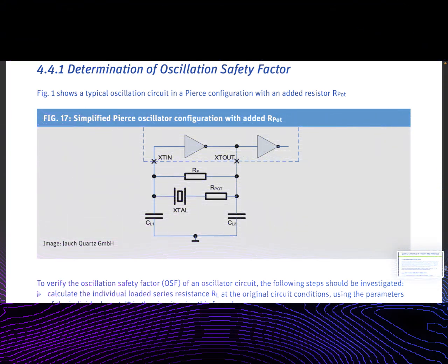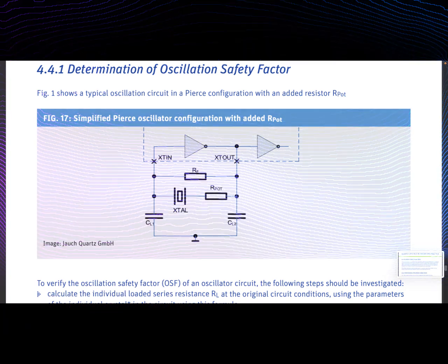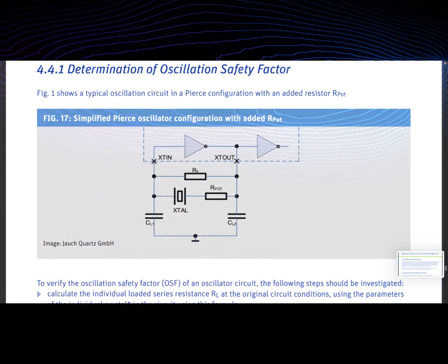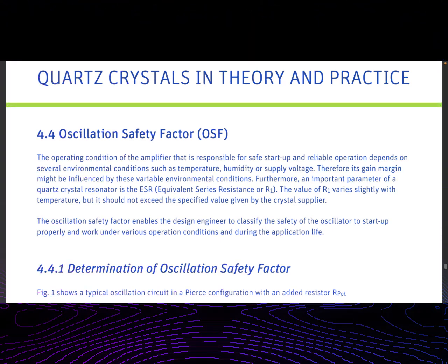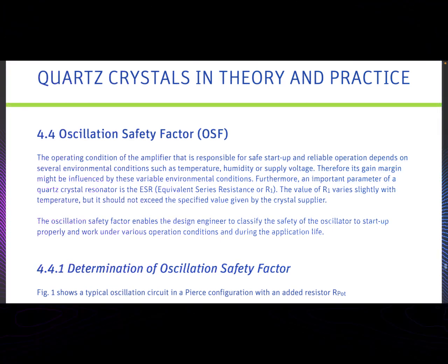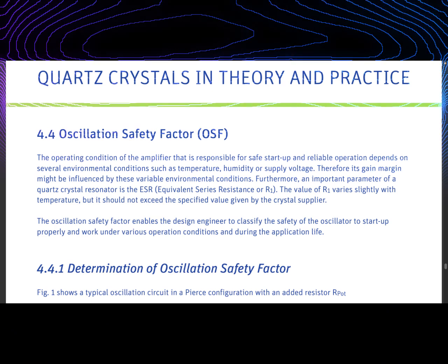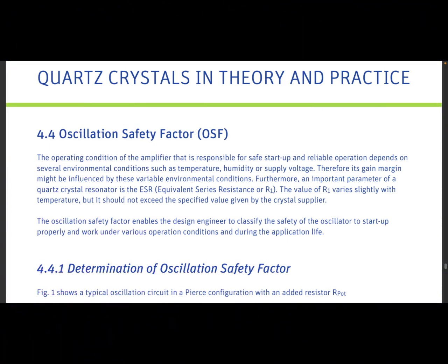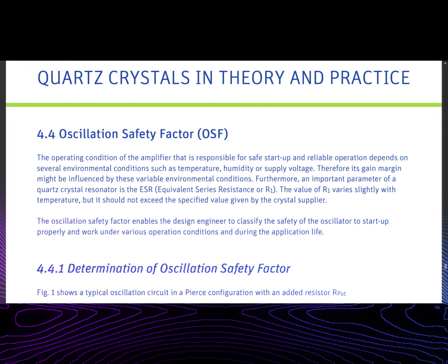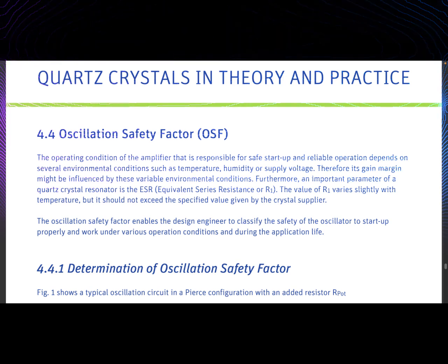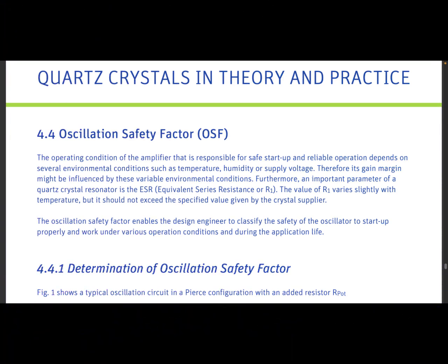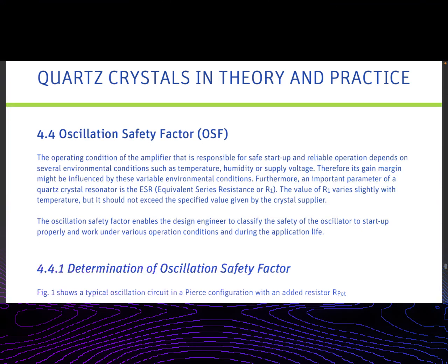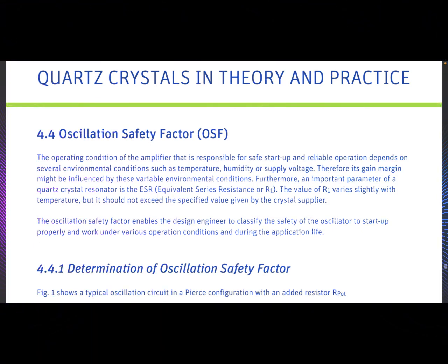The acoustic waves are traveling in the thickness direction. The major mechanical displacement is in the plane of the crystal, at a right angle to the direction of the wave propagation. In resonance, an odd number of acoustic half-wavelengths fit into the thickness of the crystal blank. Therefore, the thickness is the primary frequency determining dimension in AT-cut crystals.